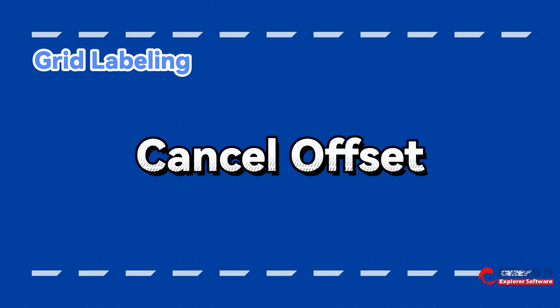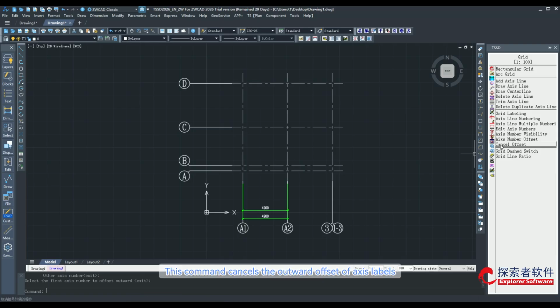Cancel offset. This command cancels the outward offset of axis labels. Note, axis labels must be on the axis NUM layer. Click the Cancel Offset function. Select the axis number to cancel the outward offset. After selecting the offset axis label, it will revert to its original position.